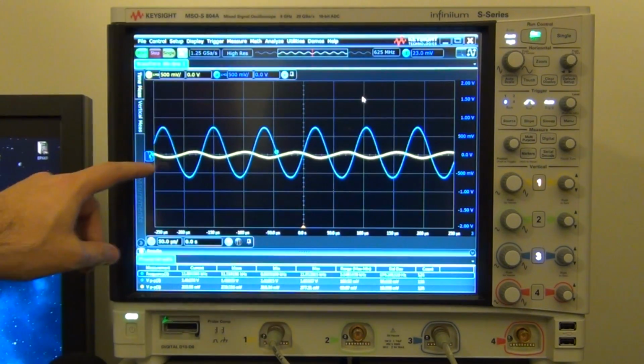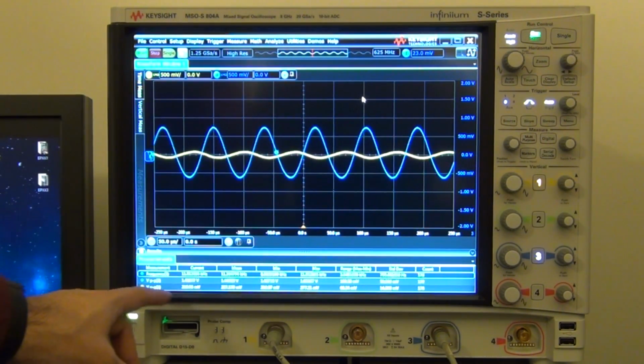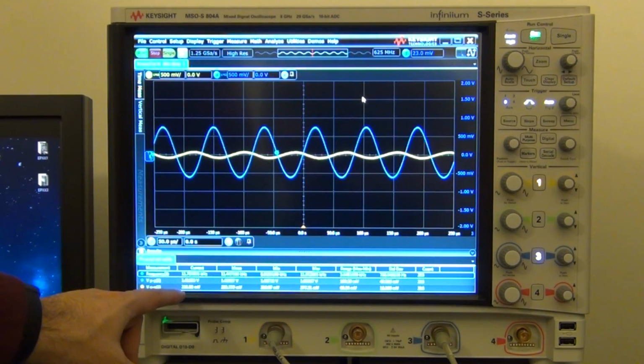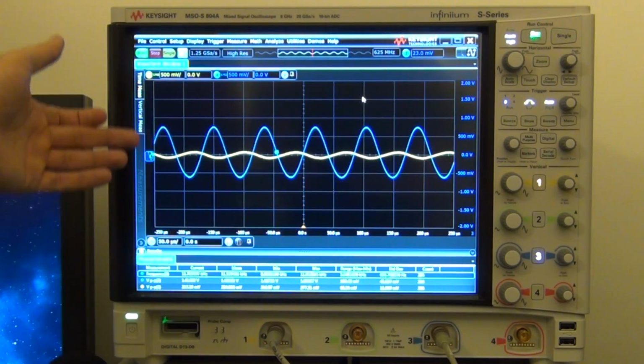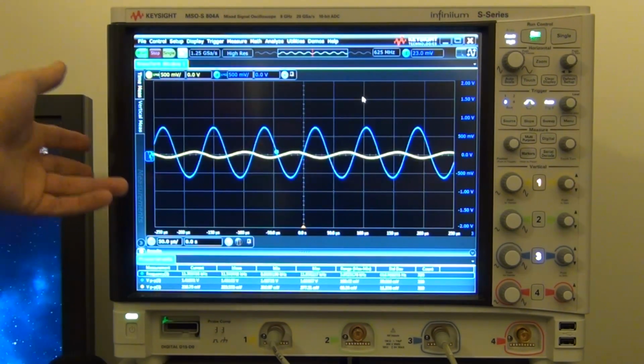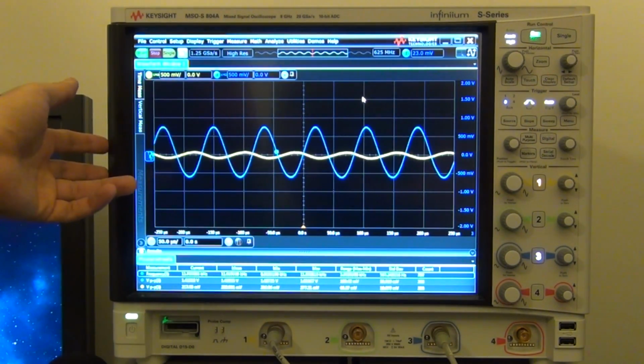Yeah, and take a look. The yellow signal is at 200 millivolt peak to peak. This is almost completely dead, but the signal coming from the transimpedance amplifier has now finally hit this 3 dB bandwidth, and the 3 dB bandwidth is 11.8 kilohertz. So we had 1 kilohertz from the resistor solution, but 11.8 kilohertz from the transimpedance. It's a factor of 11.8 improvement in bandwidth, which is extraordinarily large for this type of solution.